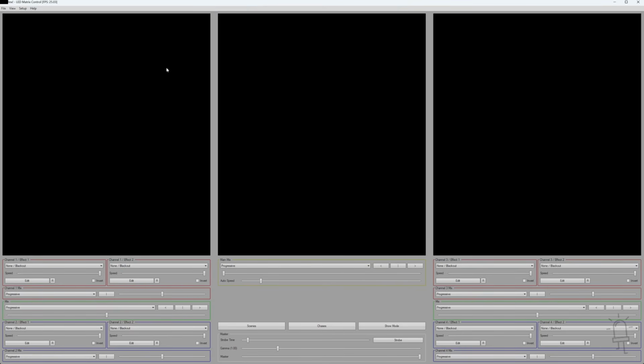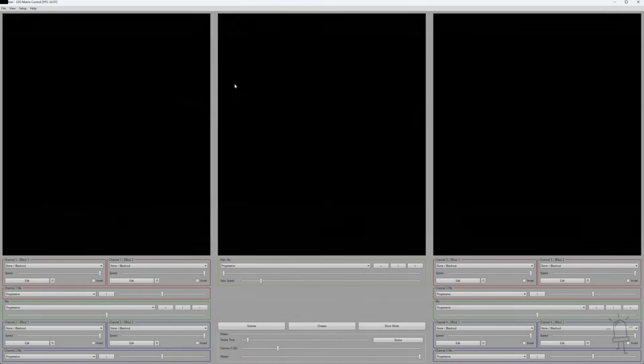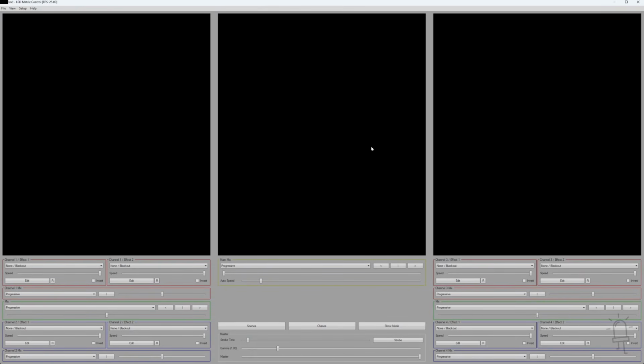Because, as I mentioned, sACN is an ANSI standard, there's loads of different software packages that support it. There's commercial software like Madrix, TouchDesigner, MadMapper, but there's also plenty of free and open source alternatives. In the video just now, I was using something called Jinx, which is specifically designed for controlling LED matrices. So let me just step through how you can configure it and some of the options available.